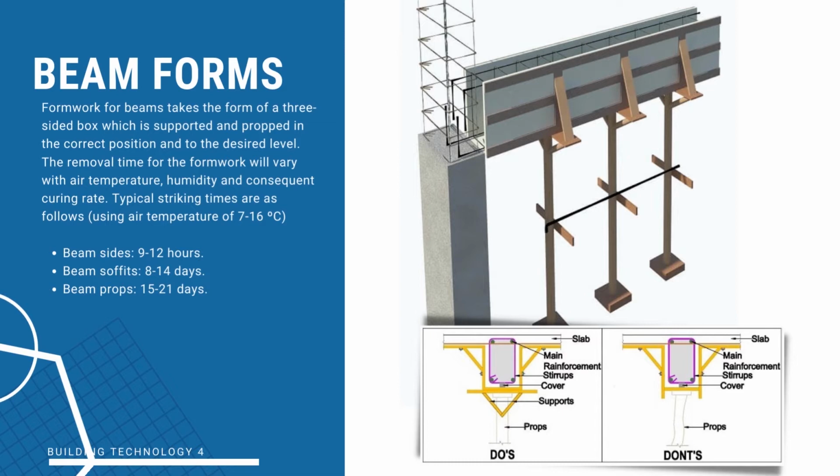Some beams can be formed independently to span walls, columns, or part of the floor slab system. So, if we call it propping, it is a system of structural members used to temporarily support loads during construction. And the soffit is generally the horizontal underside of any construction element. The picture shows that your props should be straight and not crooked. Because if crooked, the load it carries to the beam will not be properly supported.